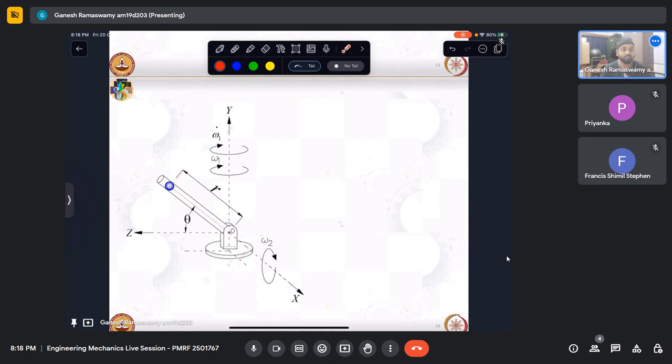The sum of those two is our relative velocity that we observe in the rotating frame, VREL. And that multiplied by cross product of that with our omega, meaning this omega, because that is what we are rotating with, will give us the Coriolis component of the acceleration.